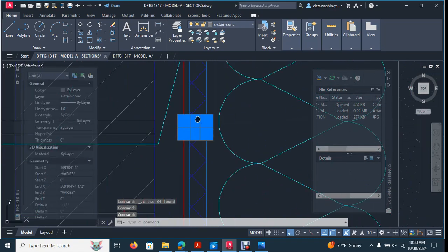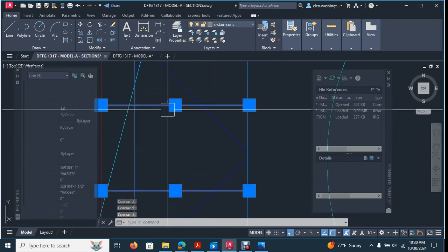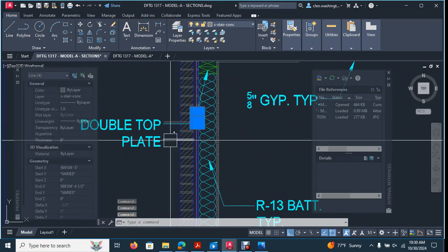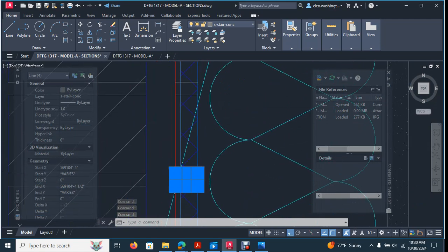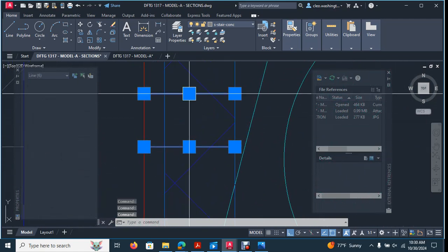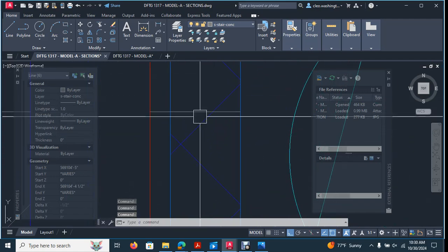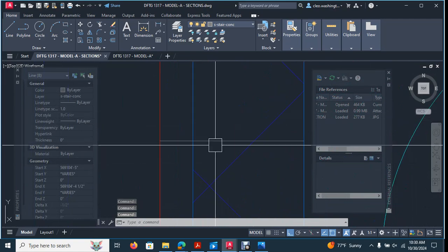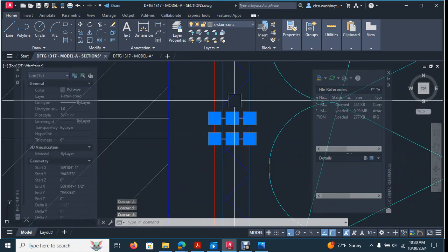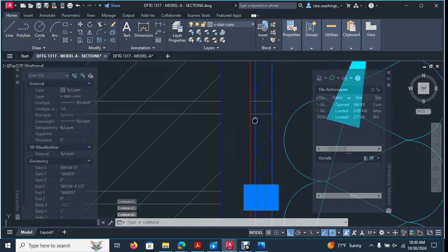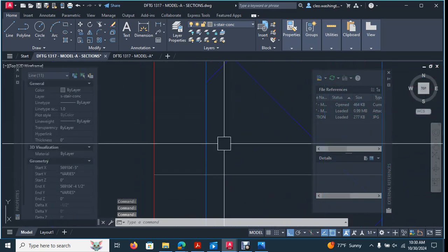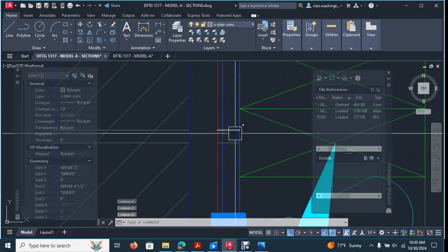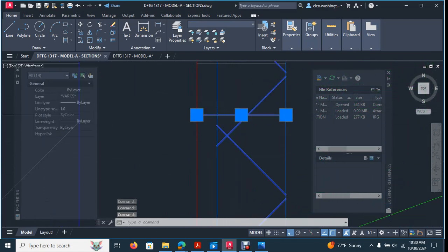It's good to select a bunch and then delete. It's notes. And then what I'll do is show you guys how to draw the arcs that represent the 3/8" mortar joint, and then we'll draw that once and copy it down.